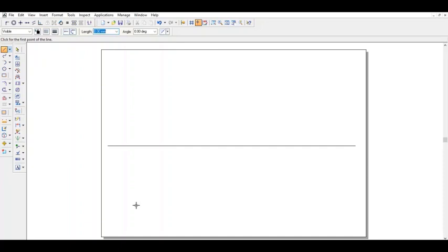So we are going to just draw a pentagon. You know how to draw a pentagon. The initial step will be 25 at an angle of 0, then 25 at an angle of 72, 25 at an angle of 72 into 2, 25 again at an angle of 72 into 3. Finally you just join to the end point of this. Later you can rotate this depending upon whichever condition is given.